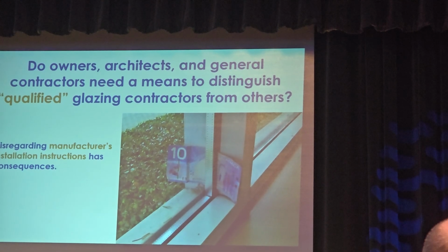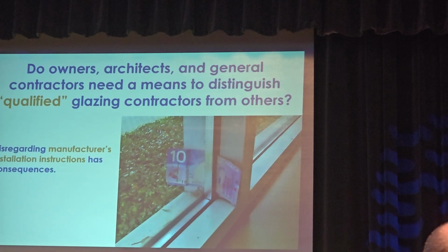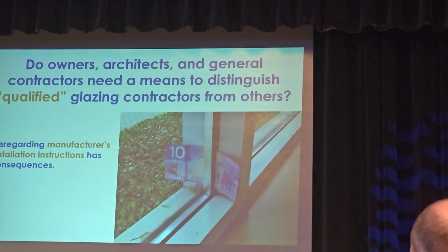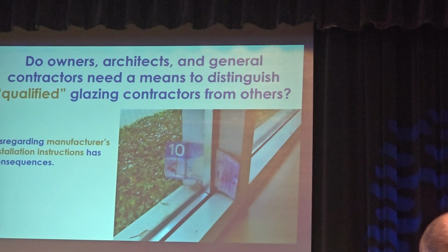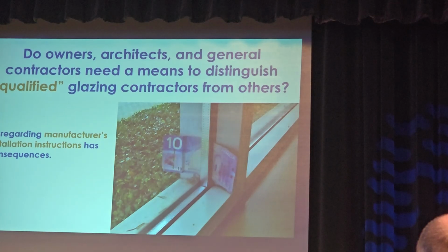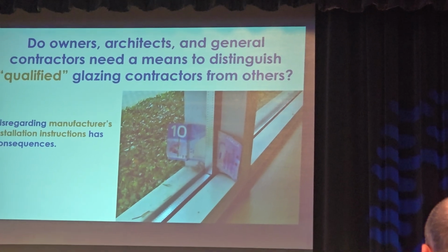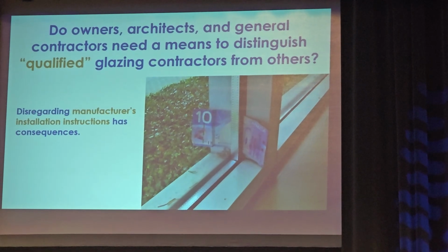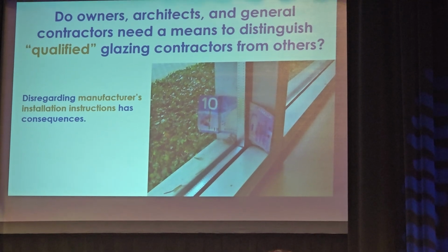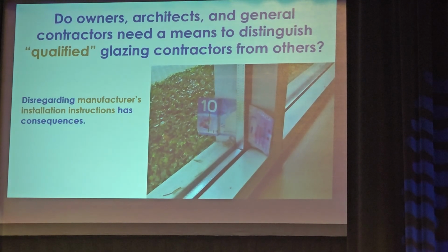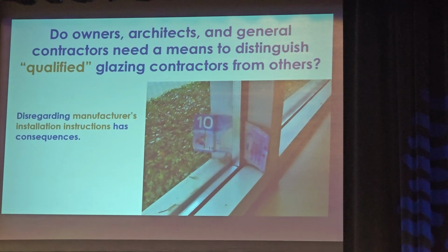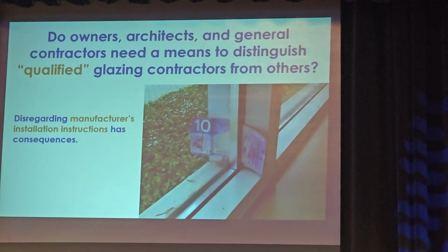My little graphic up there: what condition created a defect like that, and ultimately, what kind of problems are you going to see? There would be basically poor measurement. So if someone put glass in there, right now there's absolutely no glass plate within that frame. As you can see, that gap that's slid through there is just more reason for water to get through. And once that happens, who knows what the other side of that glass looks like. Either that glass is just the wrong size or it needs to just be pushed over beyond the rubber. So how are you mitigating that right now on the curtain wall you're working on?